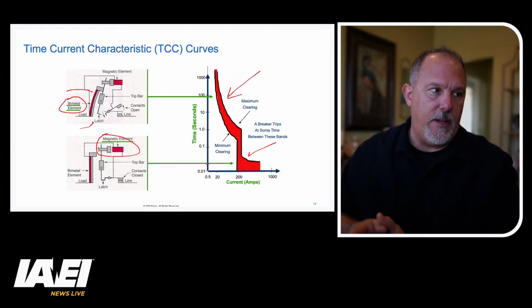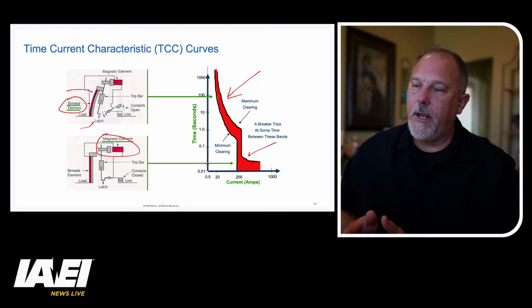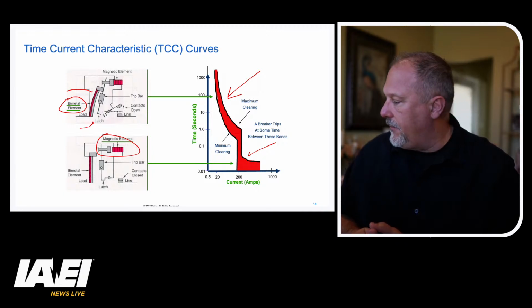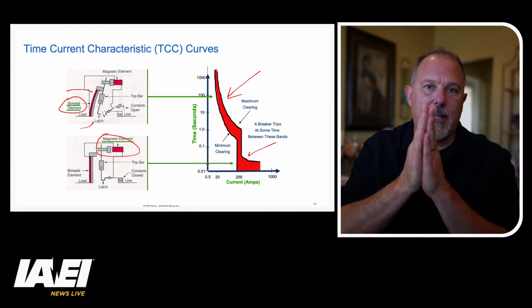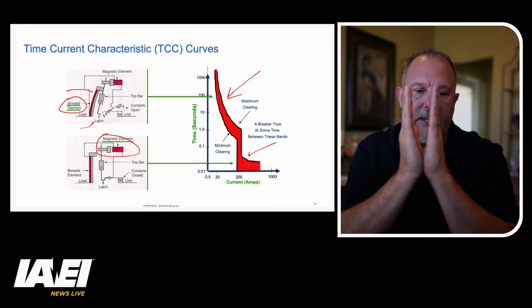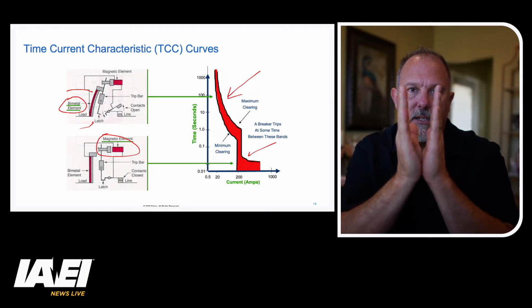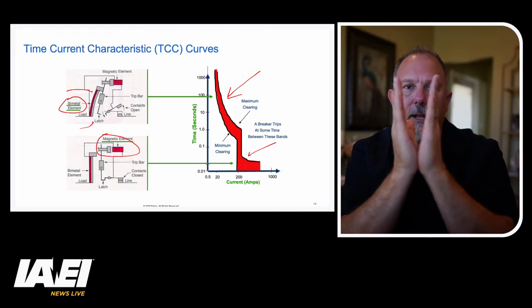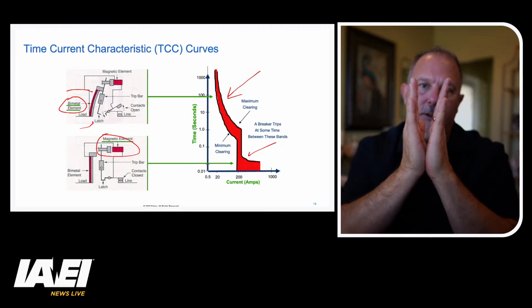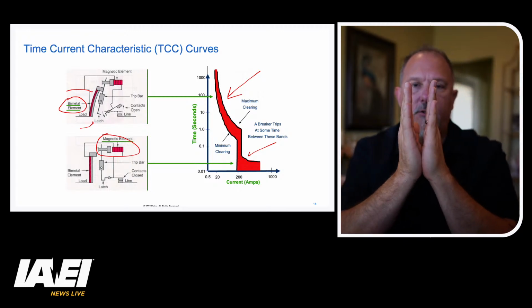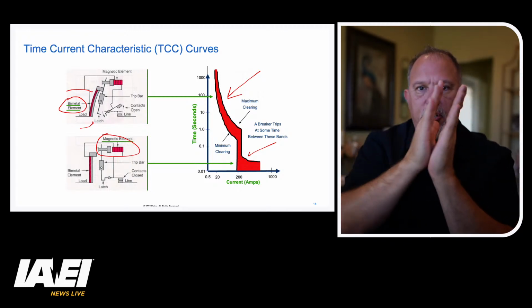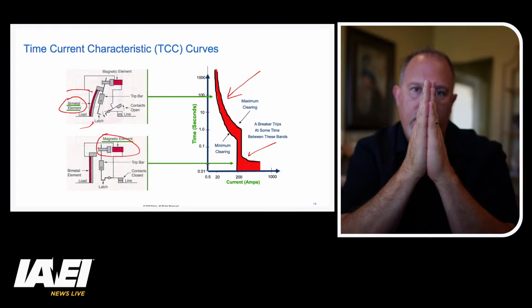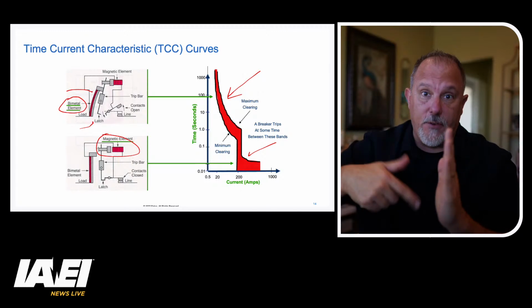And quite often in these applications, what that ends up being is I call it the clapper. You have two pieces of metal that are like this, and current's passing through this one, and the latch is over here. You're either bending the entire structure and dropping the latch, or you're pulling in one portion of it because of the magnetic forces due to the high fault currents.